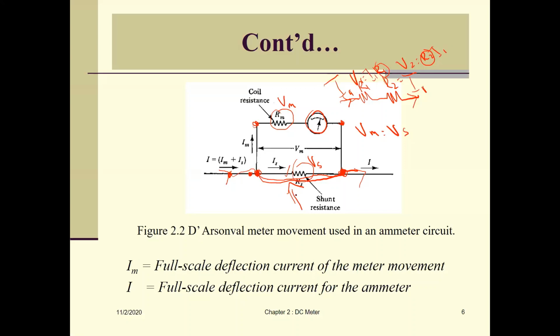It depends on the fuse. For example, our current will be high, so our digital multimeter will be broken and the fuse will blow. That's why, if you want to measure the current, make sure you connect in series, like this. We can measure the current here because it is connected in series. It cannot be connected in parallel.